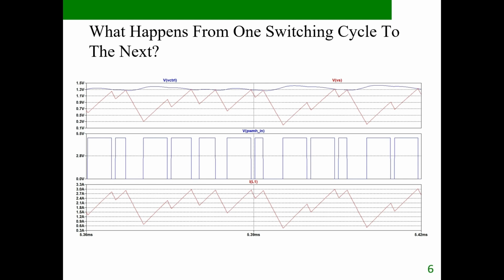Notice that the compensator output remains relatively smooth and slowly varying. The voltage loop itself does not appear unstable. The current comparator also continues performing its intended function. The sensed current still intersects the commanded current reference, and the PWM pulse is terminated accordingly.